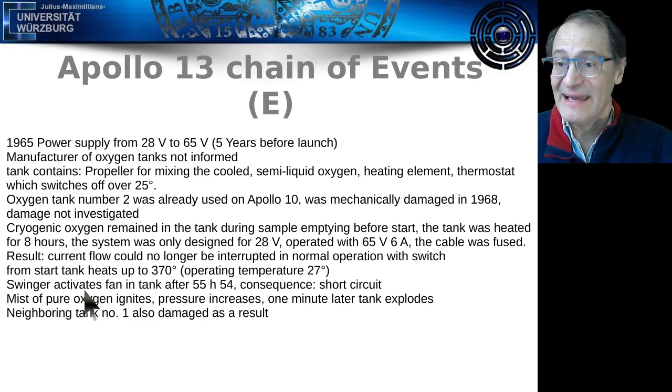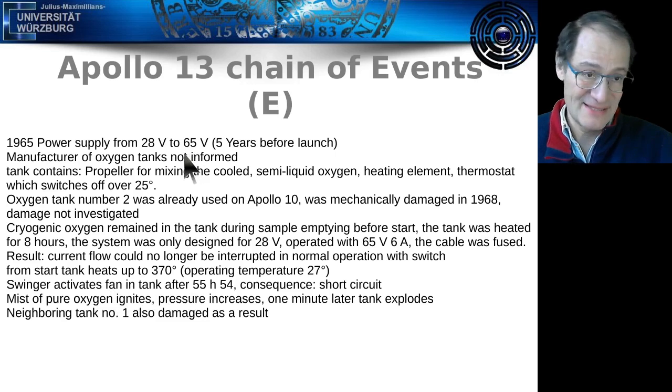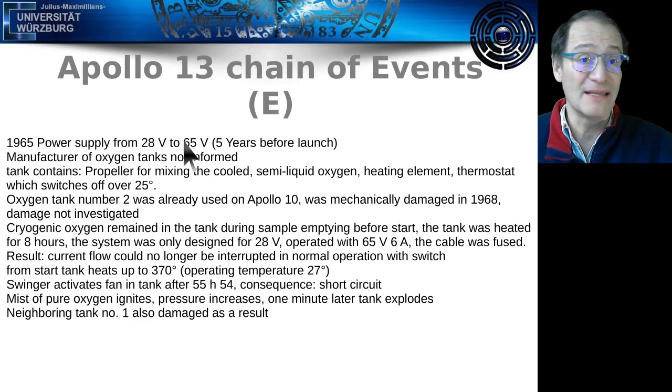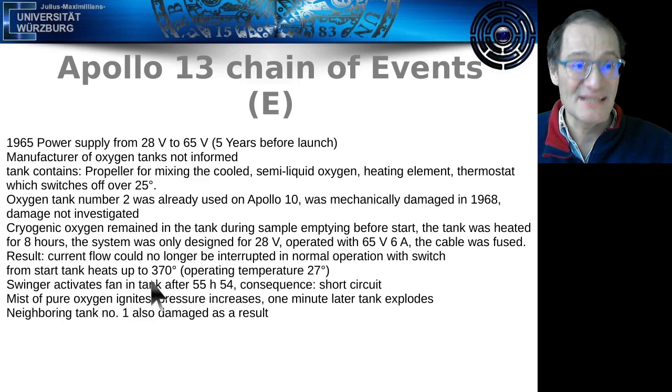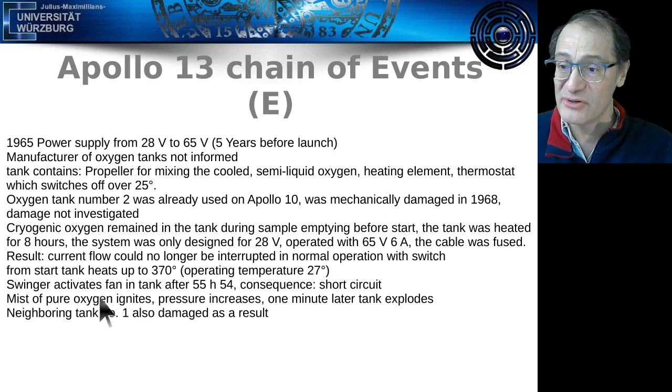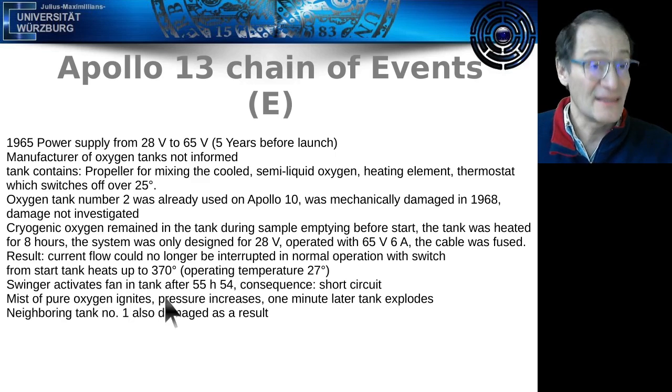And then there was a detector which detected the temperature was very high. So it started, after 55 hours of operation, a fan as a cooler. But the fan was not designed for 65 volt, the same problem as the heater. It was designed for 28 volt. So there was a short circuit. And the short circuit made a spark inside the tank, which has a very explosive mixture of oxygen. And this oxygen ignites and the tank explodes.